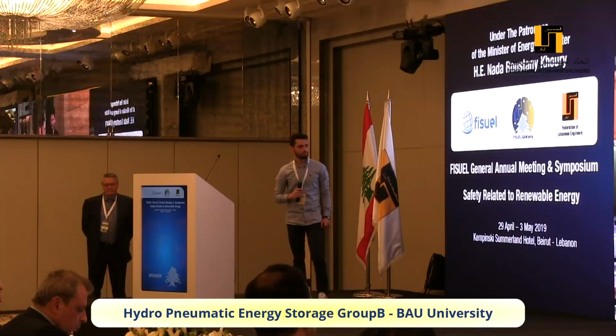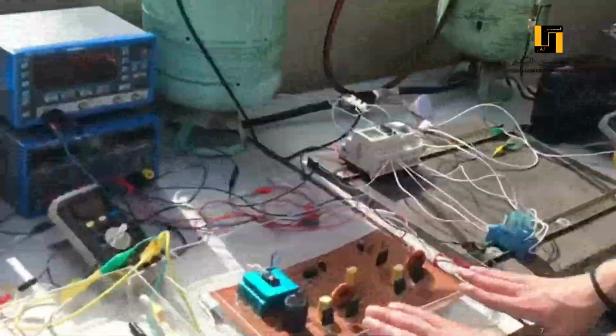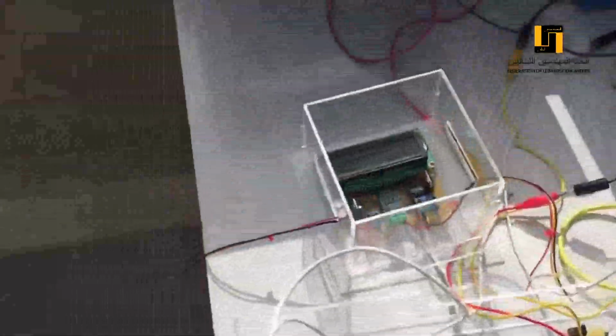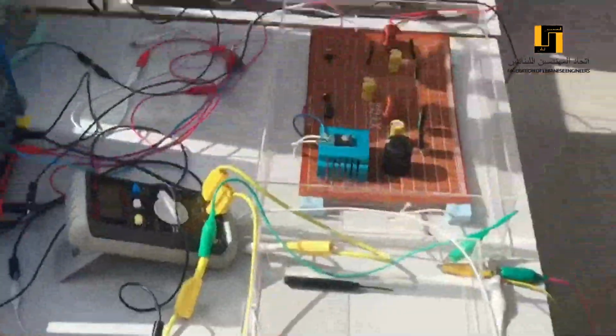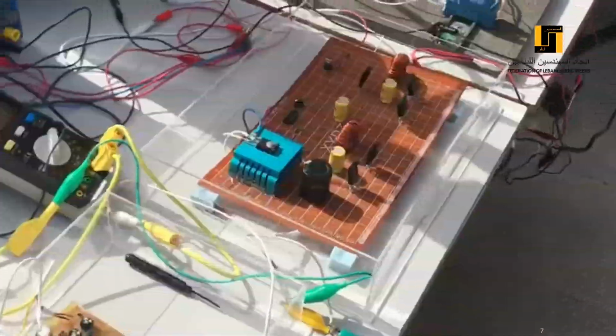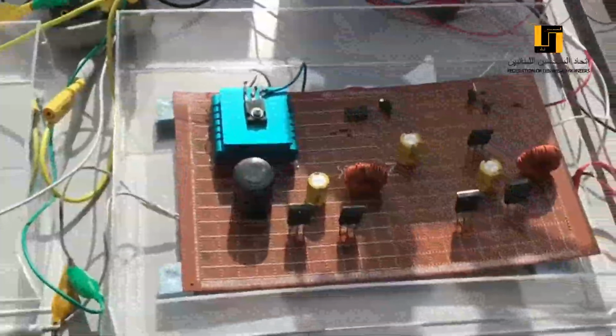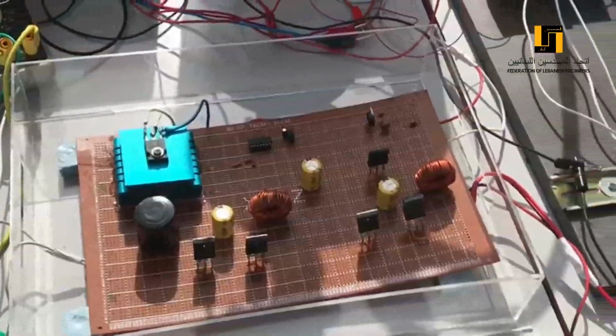Solar panel supplying a Luo converter, characterized by its robustness and low noise. The duty cycle for this converter will be controlled by a maximum power point tracker microchip controller to track the maximum power point. Now, in our demo, we will use a function generator of around 40% duty cycle to simulate this performance as we finalize the code for the algorithm, which is perturb and observe.